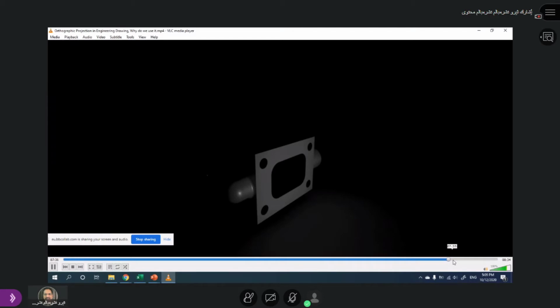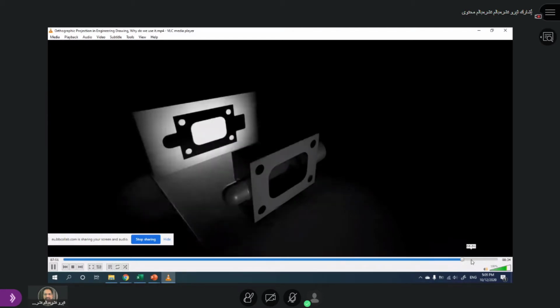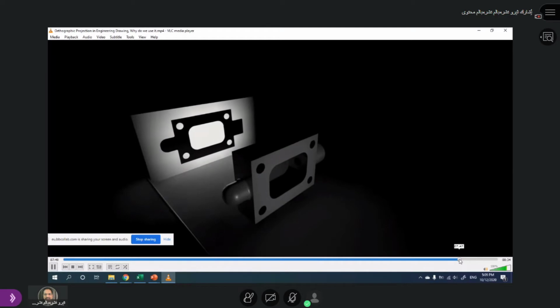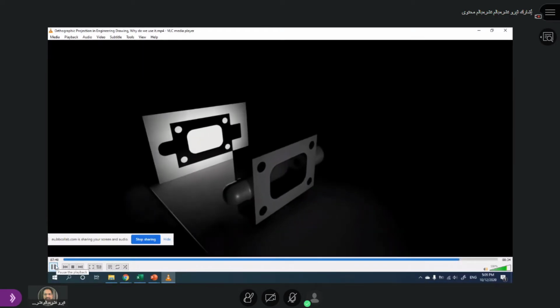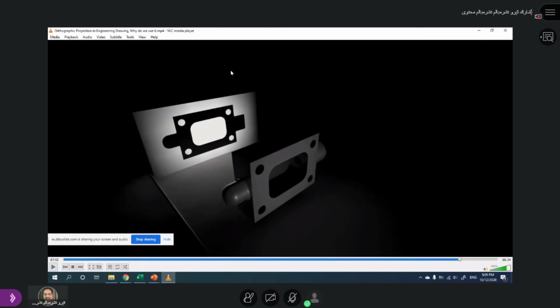Now, it's all well and good, but what I'm referring to is the profile of your orthographic projection behind it. A quick trick I can do here is bring up a piece of two-dimensional paper just behind this three-dimensional object and put a light on it. The light will trace this and show a replica of the image on the two-dimensional surface of the paper. What we have to do is highlight it, so that the shadow that's left is the profile of your orthographic projected drawing.